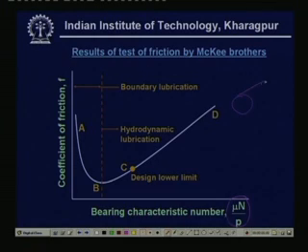This is the thing. Now, if this is a bearing and it is acted upon by some load P, then this is the diameter of the bearing. So, that pressure is the total load P divided by the projected area, that means D into L. This projected area gives you the pressure of the bearing. Considering this fact, we come to what we understand by this particular plot.